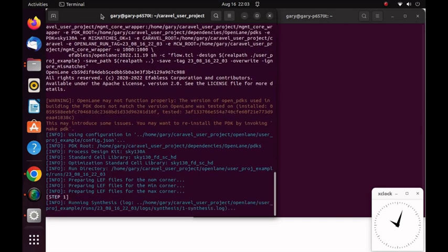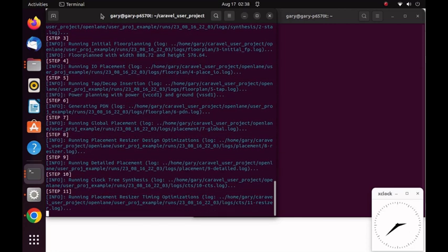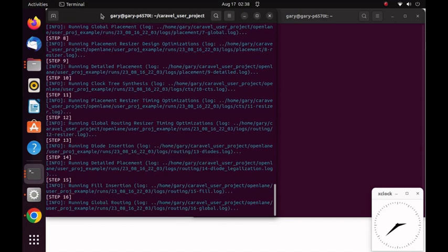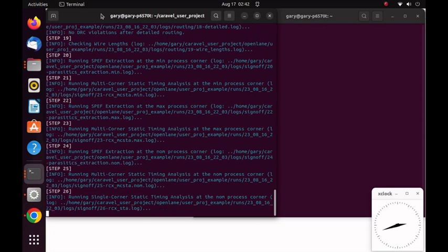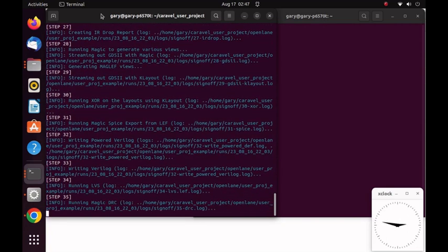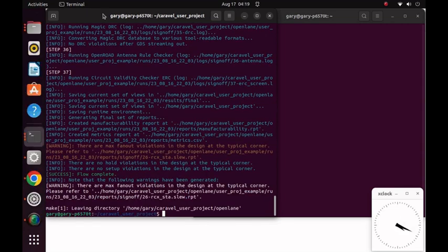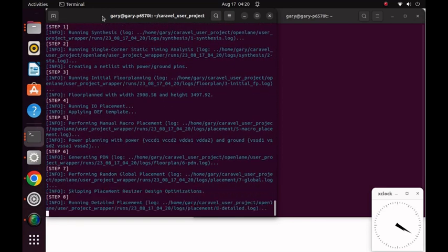It is synthesized through steps of yosys ABC RTL synthesis, OpenSTA gate level static timing verifier, OpenROAD floor planning, placement, clock tree synthesis, antenna fix-up, global routing, TritonRoute detail routing, and physical verification. The error correction coding circuit is integrated into the Caravel SoC.